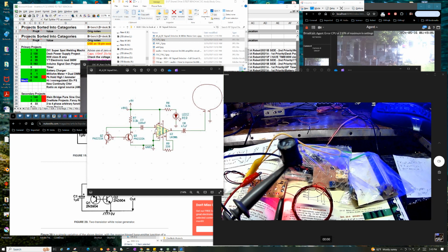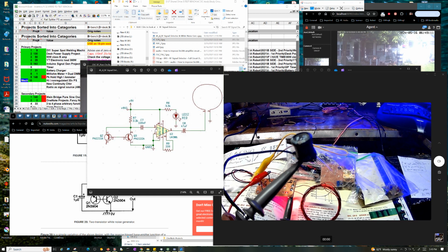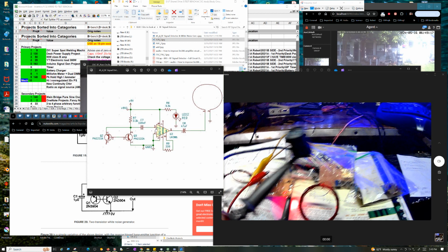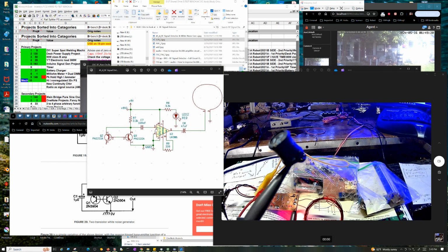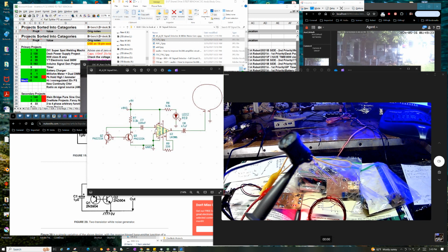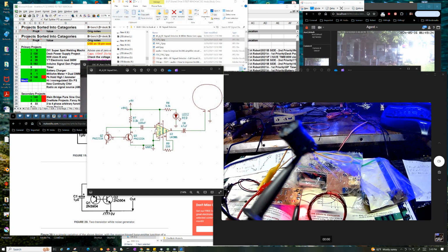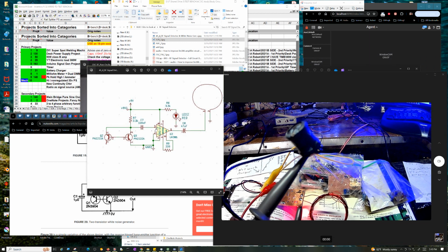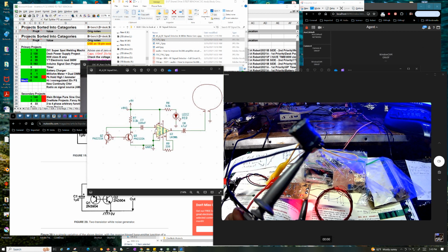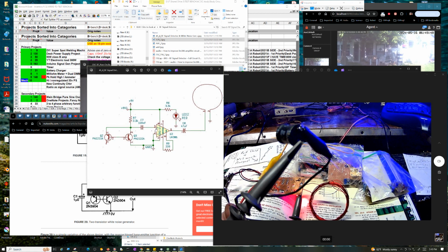But the difference between an RF choke and an inductor is that an RF choke has kind of a square BH curve, whereas an inductor will have more of an S curve. The square curve inductor is always a sign of high loss, and that's what two-terminal RF chokes do, they're trying to absorb energy. So I don't think the common mode chokes are like that, because they're designed to have one waveform cancel the other. I think that's the whole principle of the common mode choke. So I don't know that they're lossy as much as a choke is. But this could very well be an inductor. I don't know what I got it out of, but I definitely desoldered it out of something.